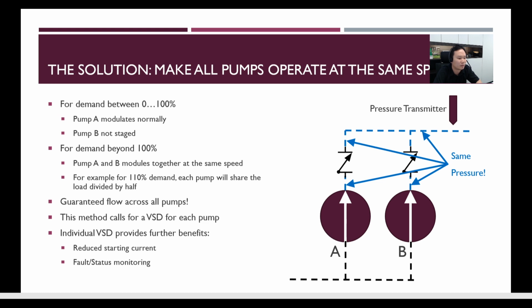You can monitor your load, your RPM, your line fault, ground fault, or something like that. In ATV310 alone, I think there are around 35 different fault codes you can use to monitor your pumps. And then using a VSD, we can provide a soft start and soft stop. The mechanical bearings and the motor lifespan will be greatly increased as well.